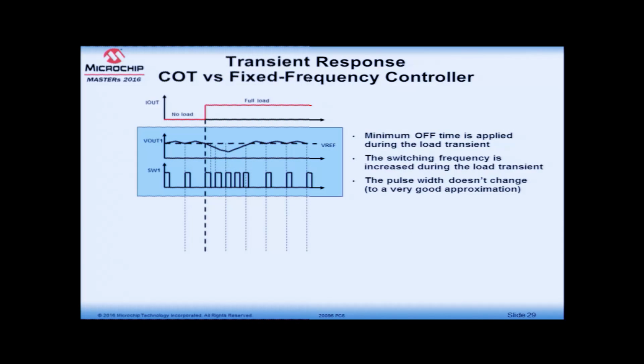One major advantage of the COT controller is the transient response, because it does not have any clock to fix the transient clocking instance. So, whenever there is a load transient, when output voltage starts to fall, it immediately initiates a pulse to correct the output, and it applies the minimum T off, as we discussed in the beginning of the slide.